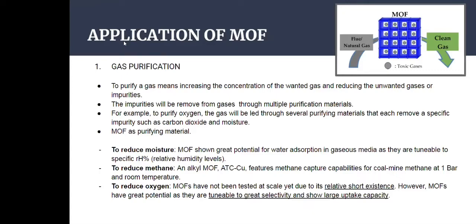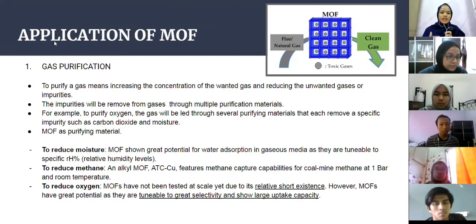Gas purification. What is meant by purify? To purify a gas means to increase the concentration of the wanted gases and to reduce the unwanted gases, or what we call impurities. The impurities will be removed from gases through multiple purification materials. Various materials can be used, however they are very selective, such as zeolite, activated carbon and MOF itself.